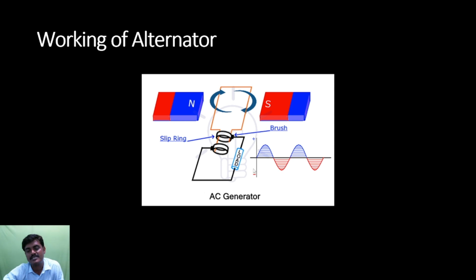So from this we can say that when the left side coil is in the north pole side, current flows from bottom to top, from the diagram view. When the same coil side comes to the south pole side, the current flows from top to bottom. Why? Because the coil moves from top to bottom, so the current moves outwards. In this way the alternating current is generated.